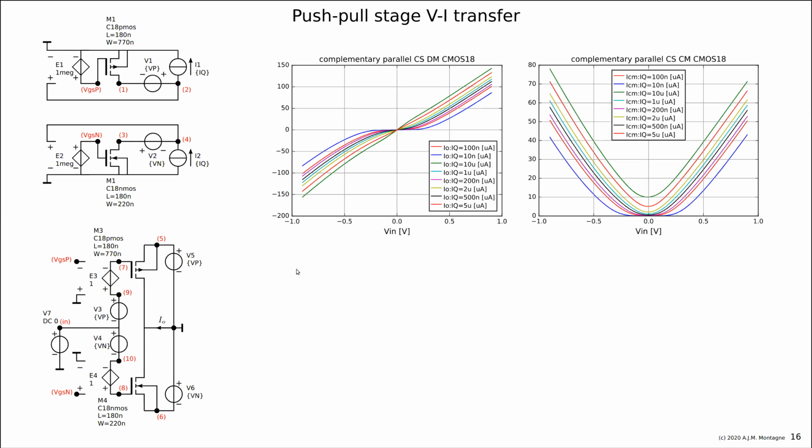So first, we have exactly the same even function for the common mode. And the common mode is now the sum of the currents through the devices, not the difference that is flowing here through the output, IO. No, the sum of the two currents is now the common mode current. They seldom call it the common mode current, but if you are really strict in the naming, then you should call this the common mode current. And again, you see the even characteristic here. I explained already the pushing and the pulling.